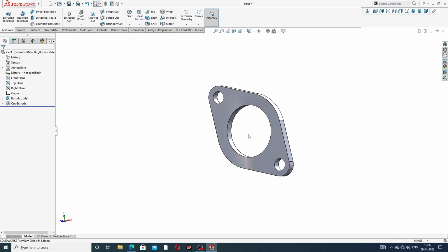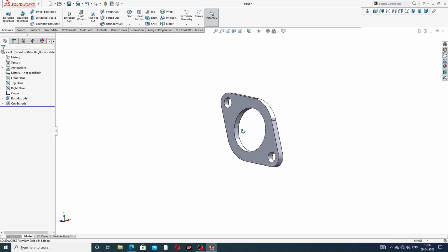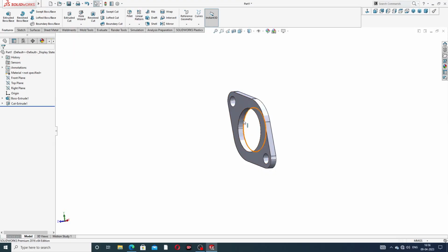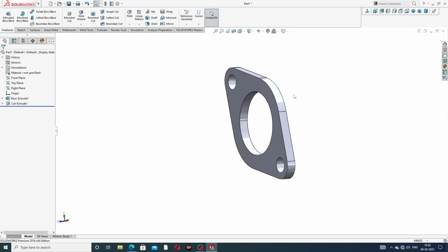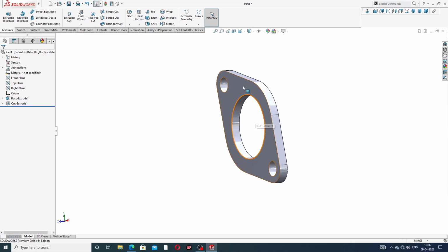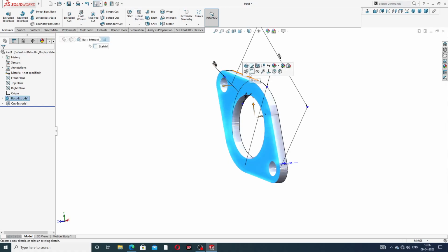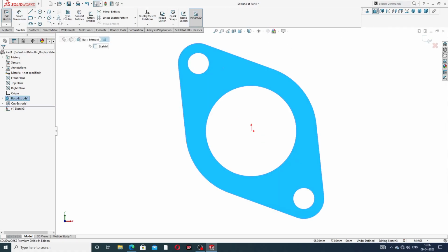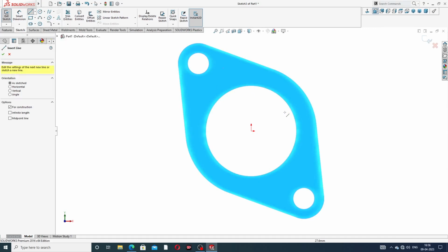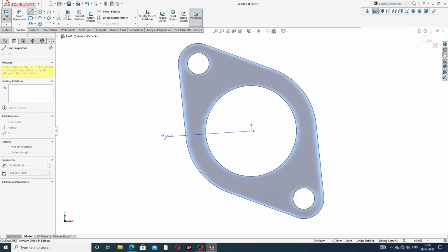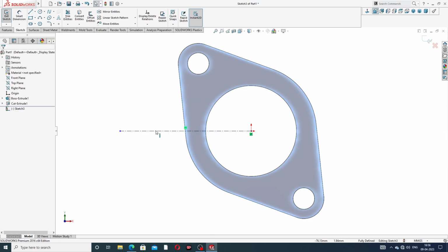But all of this is one body, a clean design, but use a pattern, and the pattern is 4, and this body is 4. Okay, and select this face, sketch normal, and use a reference line. The reference line is very important because it is used for the pattern, and this line is horizontal. Okay, this is perfect.